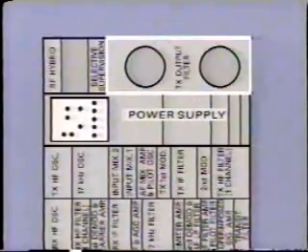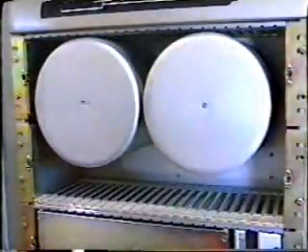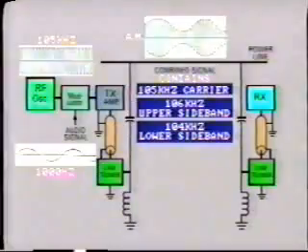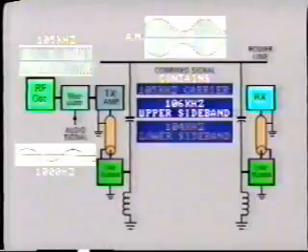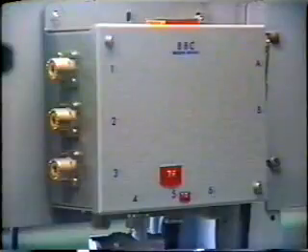This next module, the transmitter filter, is a tuned circuit that passes only the transmitter's specified frequencies. With an SSB carrier, the filter blocks the lower sideband and carrier frequencies, allowing only the upper sideband frequencies to pass through. Incidentally, some single sideband units may retain the lower sideband and reject the upper along with the carrier. The filter is provided with an impedance matching transformer with taps on the output.